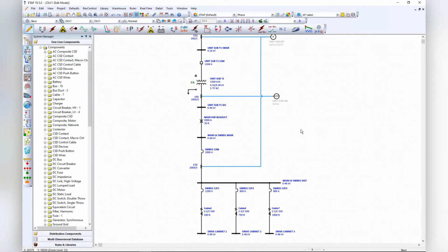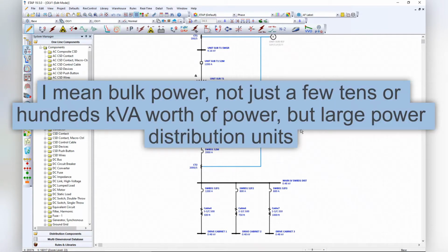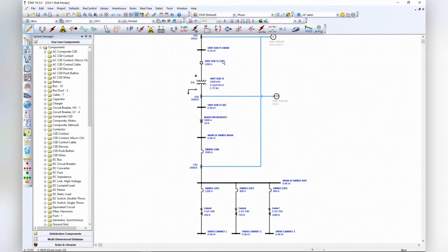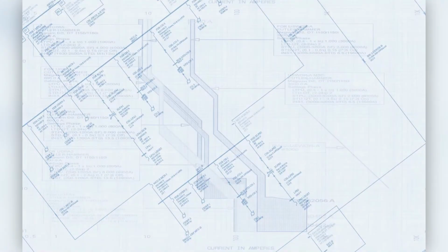And by that I mean the typical drop you will have in an area of an industrial huge plant, but you're going to need 480 volt at some point somewhere, or 4160, or any other voltage that you need. And it's just going to consist of that disconnecting means on the primary side, a step down transformer, power transformer, and then the distribution system of some sort on the 480 volt side.